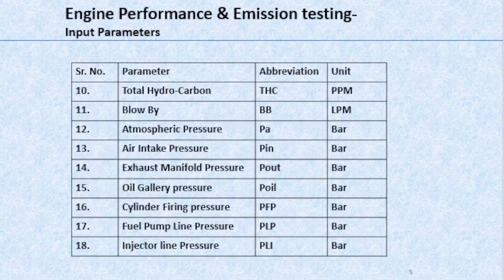emissions. Now coming to the next slide, similar to the other emission parameters, hydrocarbon, HC, is one more pollutant to be measured. This value will again be converted to specific emissions. You will get a complete understanding of engine performance along with emission performance, as I mentioned earlier. Blow-by is flue gases escaping from the piston, ring and liner areas. These parameters do not take part in emission calculation.